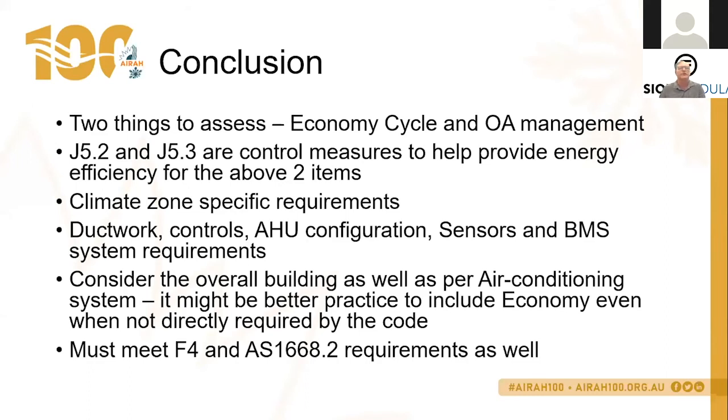Design AC supply air quantity will change based on supply air temperature for a given load, potentially changing the requirements of the economy mode. So any requirements for design supply air temp to be fixed in the BMS? No. VAV systems will vary supply air rates.